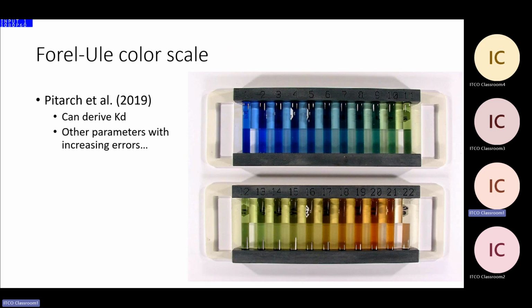So there's another very inexpensive method to judge the color of the water, the Forel-Ule color scale. If you have ever used this, you can see the picture here as well. This is a version that you can buy online, but you have these numerically distinct color types that Forel and Ule came up with. And you essentially put your cartridge in there, and then you look through here at a white Secchi disk in the water, and you can get the color.